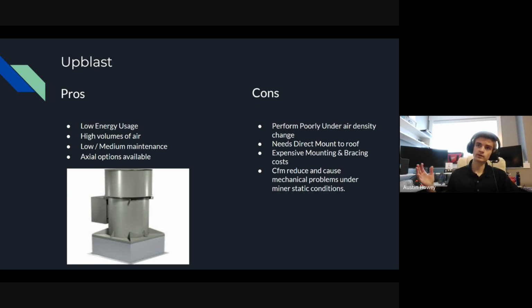so that when there's air or wind that blows past those fans, it at least has some time to build up its static pressure and its velocity in a vortex motion going up into the atmosphere. So it holds that hot air up in the atmosphere as opposed to holding it lower down. And that's where a lot of problems happen. I'll see people run these fans right off the roof, and they'll be panel fans, but then the velocities aren't high enough, and it'll go right back down to their intake.